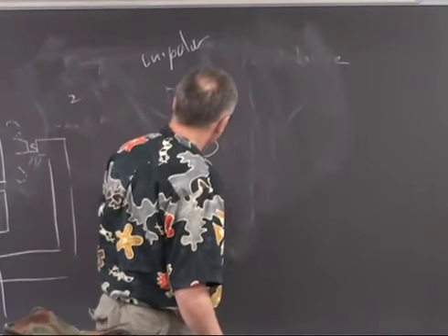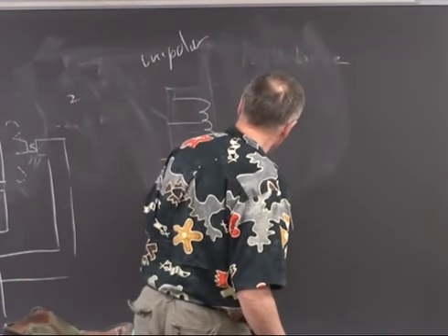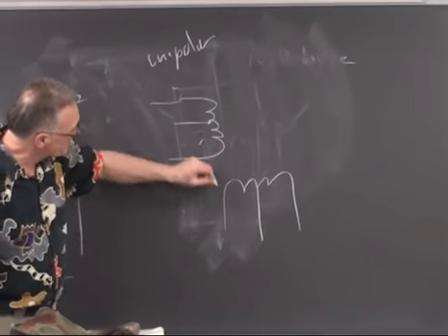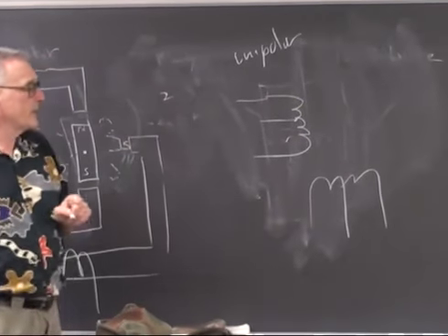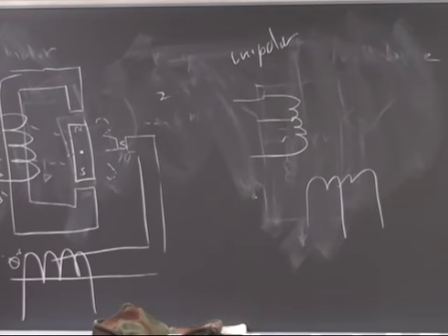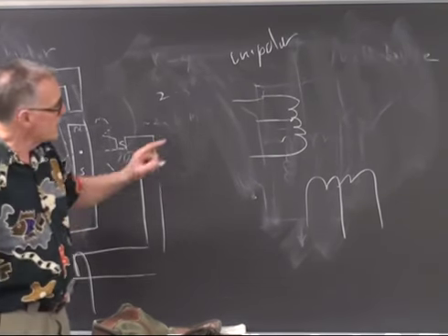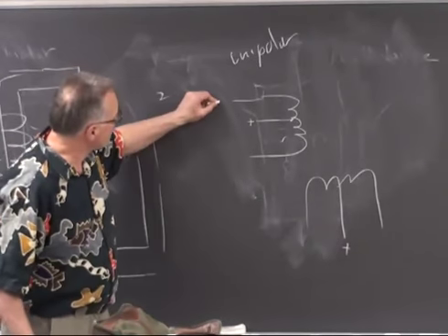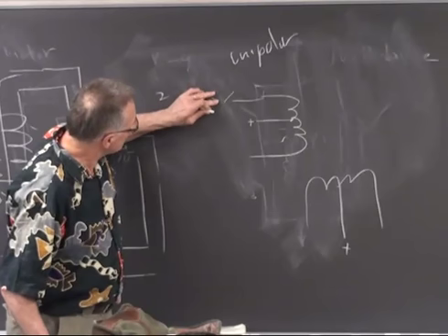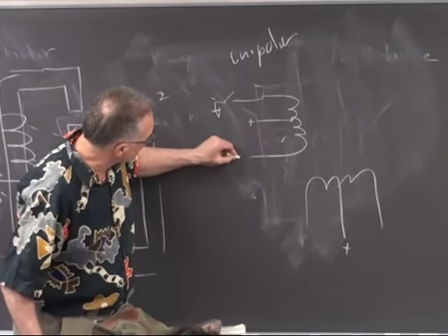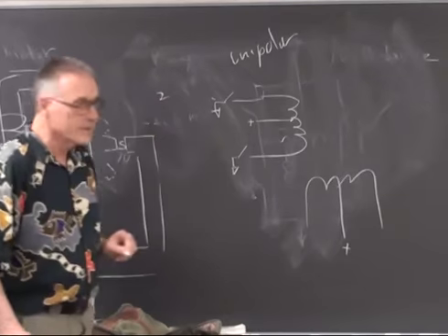and they have a coil structure that looks like this, where you have a center tapped coil on each phase, and you either drive current, typically you wire this to the plus, and then you either ground this side or you ground this side.